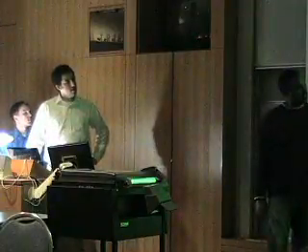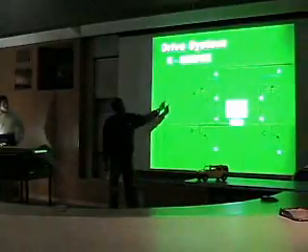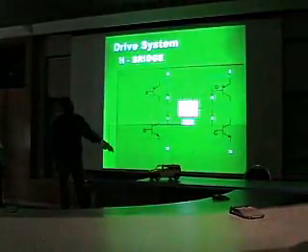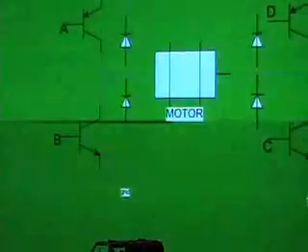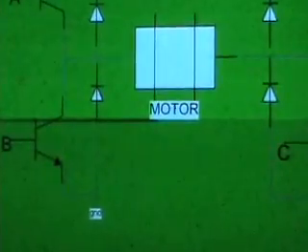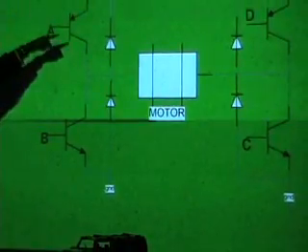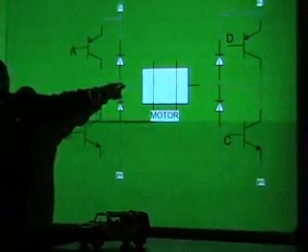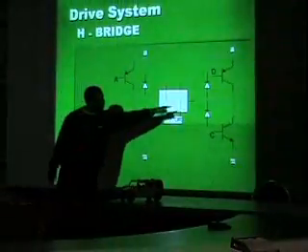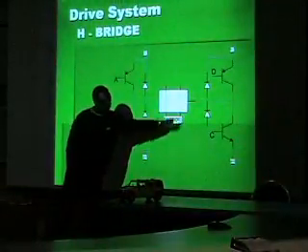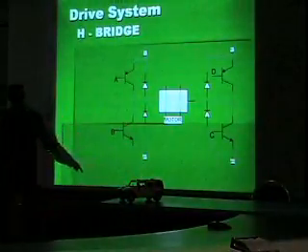This particular part was the H-bridge. It has some transistors and resistors. This is a high level diagram of the H-bridge. And the C and the T are connected together, and the E and the T are connected together. When the PIC signals, this side of the motor gets 9 volt, and this side will connect to the ground and turns one way.